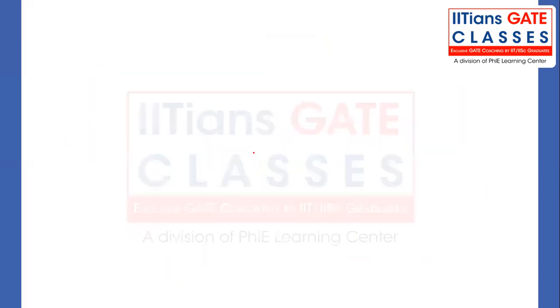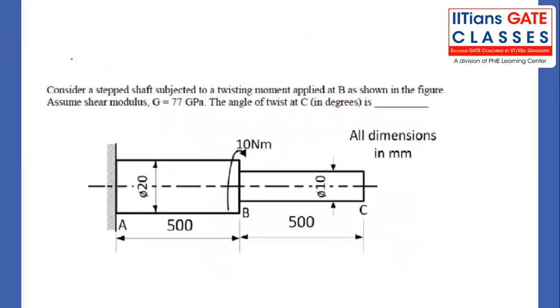Now, we will try to solve this numerical also. Consider a stepped shaft which is being subjected to a twisting moment, something like this. At the B point, shear modulus is given, and they are asking what is the angle of twist. Angle of twist at C, we can write as angle of twist C with respect to A. Whenever they ask you the angle of twist, you have to calculate it with respect to the fixed end. Phi C with respect to B plus B with respect to A. We can write like this.